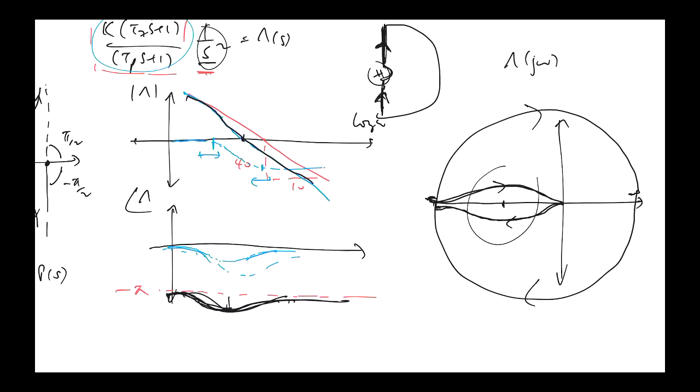point. The critical point will be inside here, right? No matter how you choose the location of the controller pole and 0, no matter how you choose the gain and make this shrink and expand, the Nyquist plot will always look like this, giving you 2 clockwise encirclements of the critical point, right?